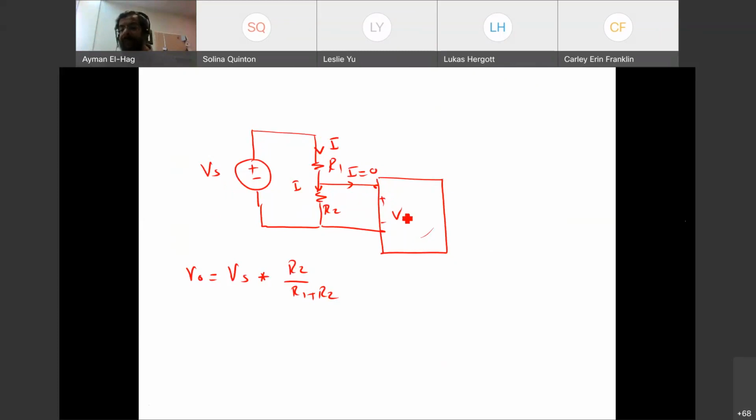I don't want this measurement system to have a small resistance. Otherwise, it will take from the current in the circuit, and the whole circuit will be changing because my measurement circuit is interfering with my circuit, and it should not. It should measure the voltage without consuming any current from the circuit. This is why I need this to have a very, very high input impedance.